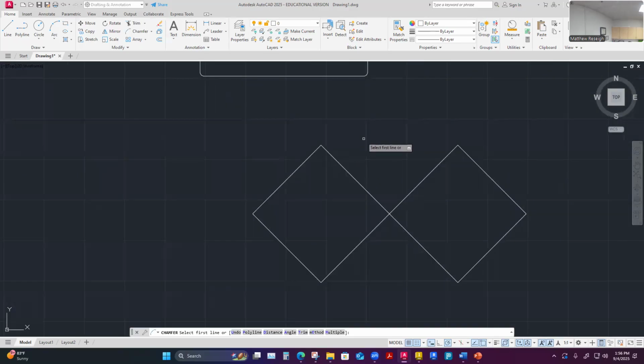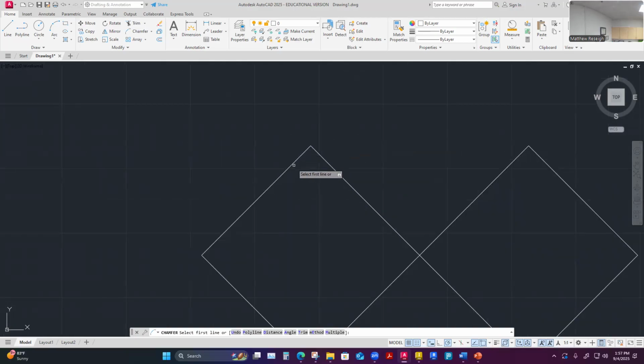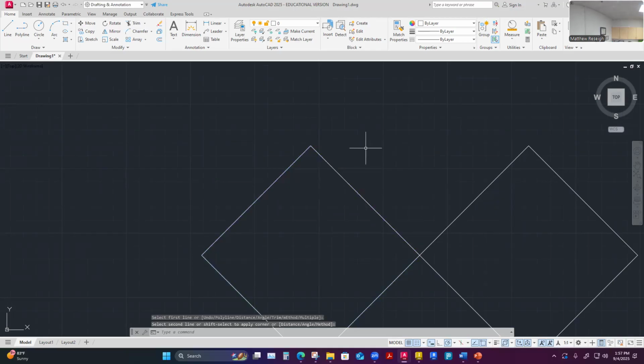We'll see chamfers and fillets a lot. So first line, I think it's similar, it's a little bit different. I mean, it has some similarities. If I just want to see what it's doing at default, I would choose here, I would choose here. Nothing would happen because its default is also zero. Just like fillet's default was zero, chamfer's default is zero. If we're going to actually chamfer, we need a distance.